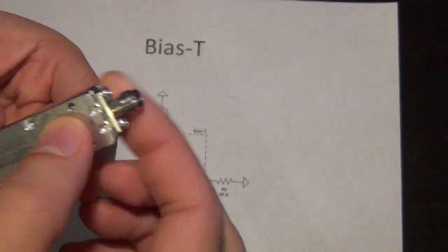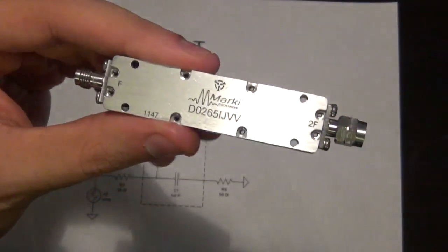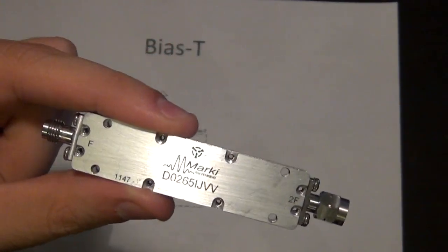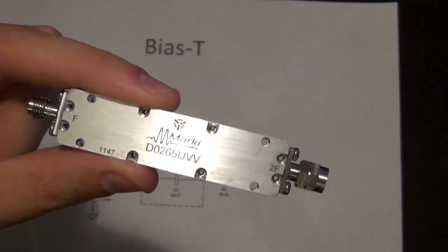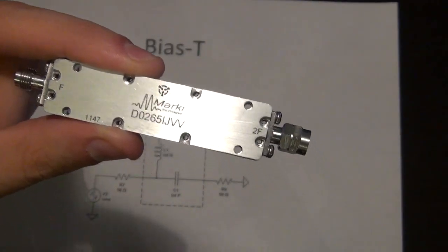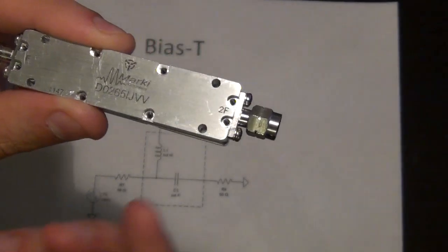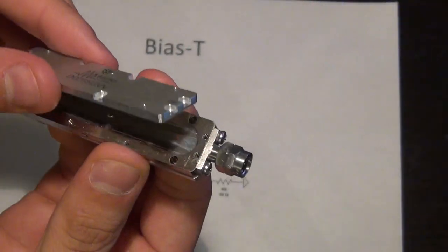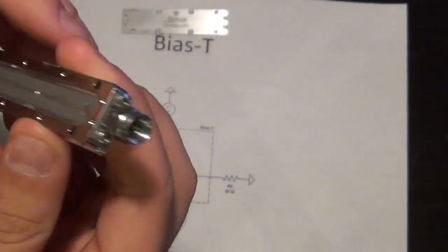Now, what would we expect to see in this? Remember, this has no DC ports. It's purely powered by the RF signal itself. So what is an ideal thing to use in a situation like that? If you remember from one of my previous videos, when I did a tutorial on linear and nonlinear circuits, there I used a diode, and that's exactly what they do here too. But they use a very high frequency diode.